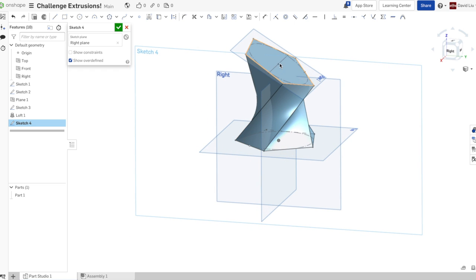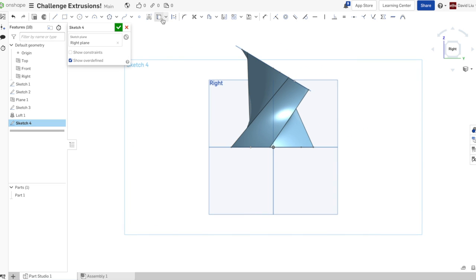If I take this shape, for example, I can copy this line onto the sketch plane without actually having to draw it. So let me press N again. The ones we're going to have to project right now are the midpoint for this and the origin right here. Projecting those, we create 2 points. Using those 2 points, we can connect a line through them to create our path.